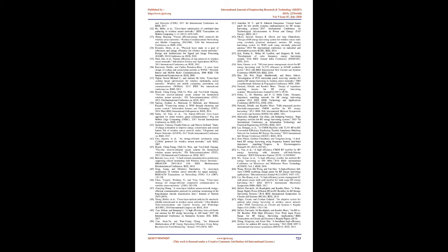Wang Y et al. 2014 proposed a radio frequency harvesting scheme using a floating gate cross-coupled, FGCC, rectifier structure to achieve better performance at low power levels. The 3-stage FGCC rectifier uses low threshold voltage, LTV, transistors so as to maximize the efficiency. For 850 MHz input AC signal, the PCE attained is 70% at 20 µW, -17.0 dBm, input power.